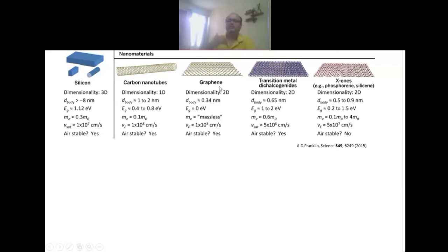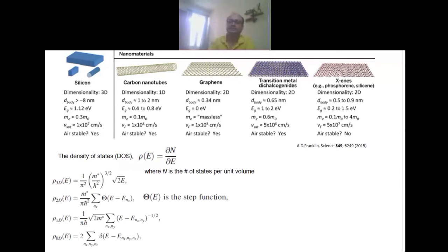So in a semiconductor, if you give external heat, then conduction can happen, so the resistivity will be decreasing. The opposite tendency will be there. If you have a clear understanding of how the band gap forms by overlapping of the bonding and antibonding states of different atoms, then you can really understand why in a semiconductor the resistivity decreases with temperature, while in a metal it is increasing in nature.